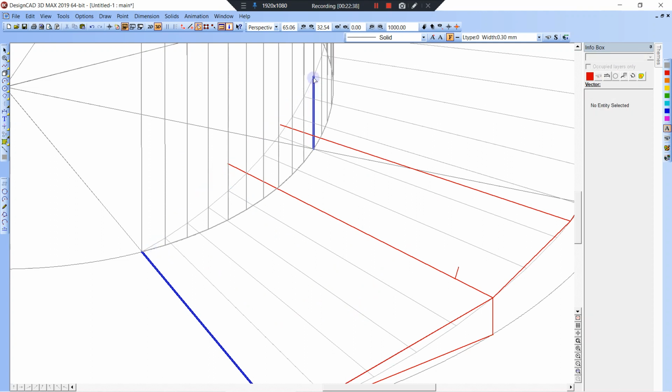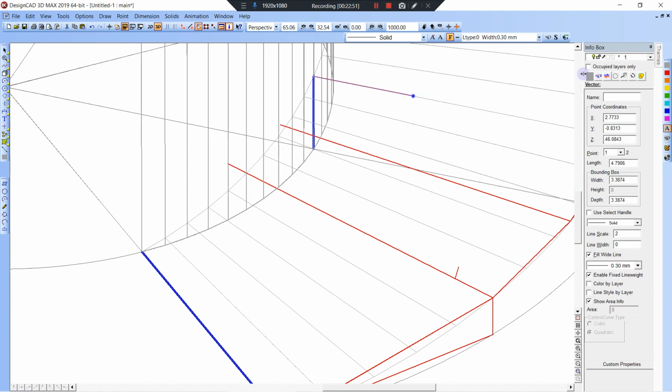Now you have this column and this column, so what you do is you pin a nail there, let's say, and then here you would use the ground. Let's do it the other way. So V, H, K, enter, and let's turn this into a purple, apply, and we want the length to be 4 feet, enter.